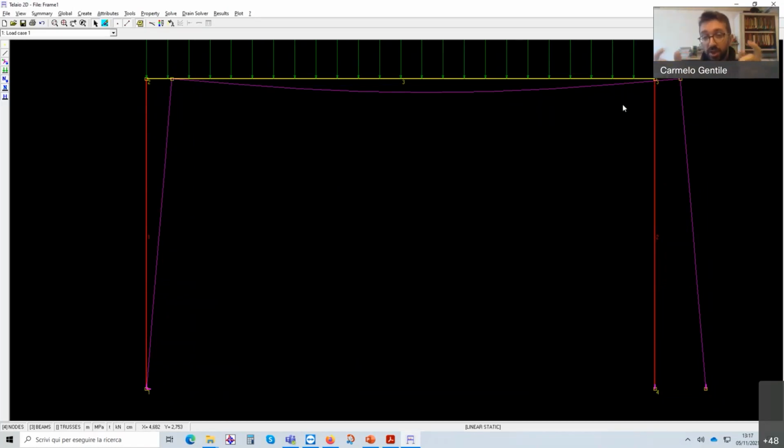This rotation means that we are transferring some curvature, but not the beam 1 and the beam 2. Since we have a fixed section here, they have to share the same angle, so it must be still 90 degrees. So if we have a horizontal deformation in the beam, we expect also a vertical deformation at the beginning of the column.